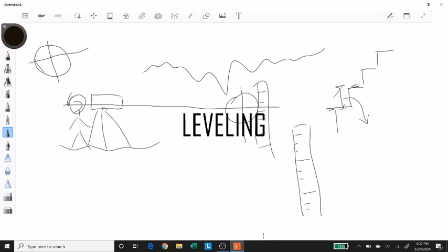Although the graduations are very small, since it magnifies your vision, you get an enlarged view of these graduations on the leveling staff. So what you would be looking at is a reading. If your crosshair gives you this, and if this is 4 and this is 3 meters, you'll be reading a value.